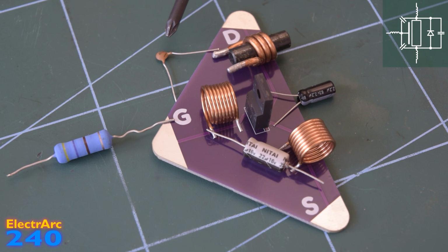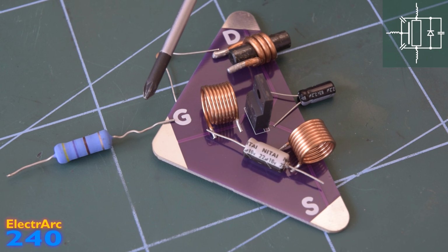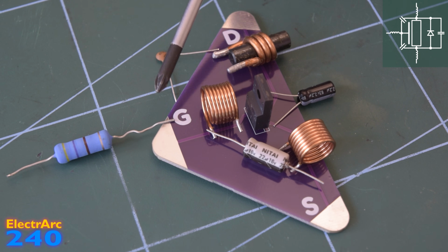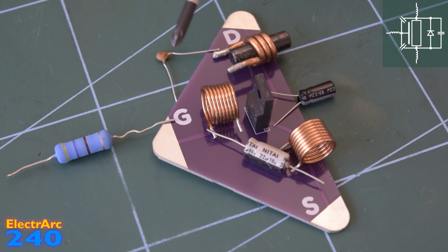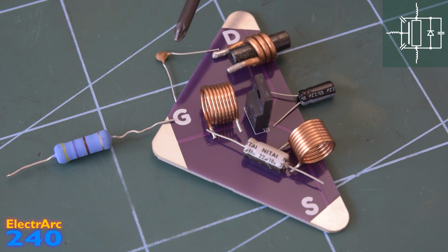Because of the capacitance's desire to keep the voltage across it the same, when the drain voltage shoots up, this capacitance tries to bring the gate with it. And I'm sure you're already shaking in fear at what this could cause. The gate being pulled up to 400 volts is going to destroy the MOSFET instantly. Well, this is an effect known as Miller turn-on, and because of that name, this is also often referred to as the Miller capacitance. The effect of Miller turn-on has become a much bigger deal recently, with the advent of silicon carbide MOSFETs, which are both higher voltage and faster switching than conventional MOSFETs.